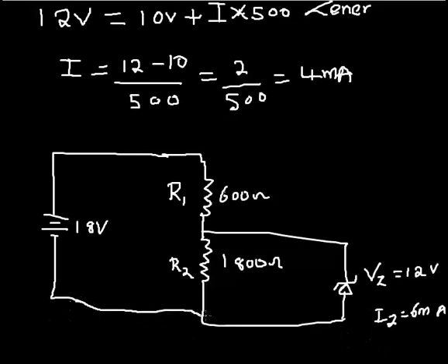That is the voltage that the Zener must take before it operates. And once it takes this voltage, then it will remain at this voltage throughout this current. So once you supply this 12 volts to this Zener, then definitely you have this steady voltage across the Zener. No matter how much you increase the supply voltage, this is the voltage the Zener will deliver across it.